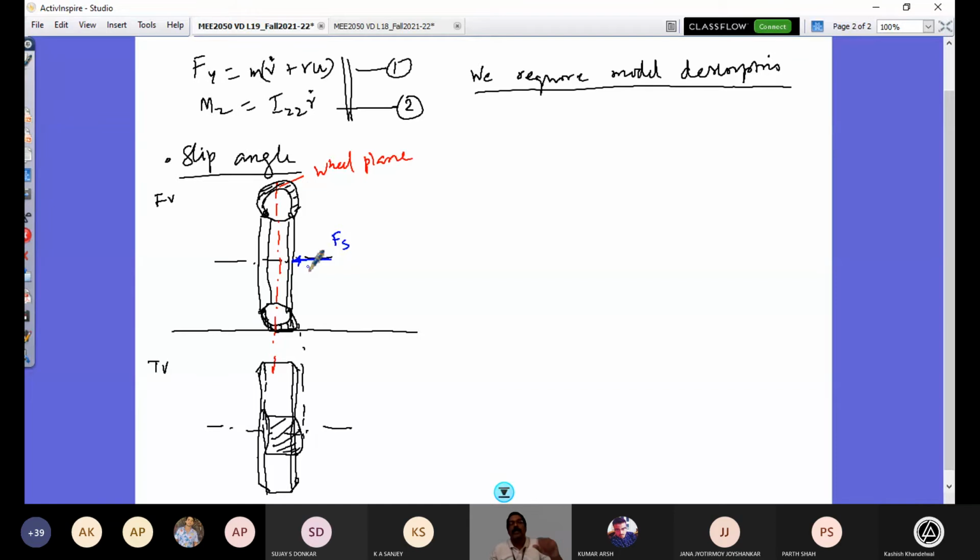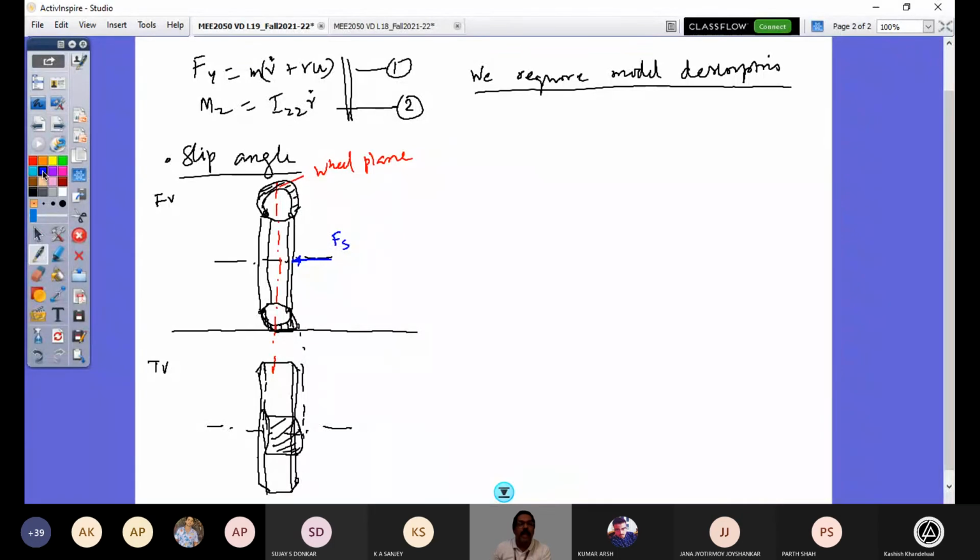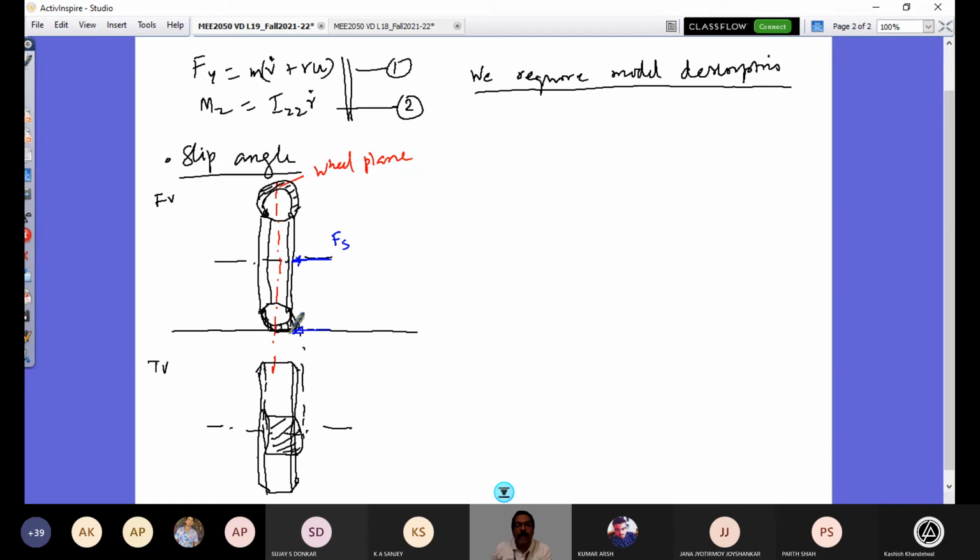So this force is now going to create a force here down, right? You have studied in your rigid body mechanics what is called an equivalent force couple system. So what am I going to do? I'm going to bring this force down and cancel that force. So the system is same. Of course, my intention is not to draw a full free body diagram, just showing some forces at the moment to understand. So this Fs is brought down here, and this Fs here.